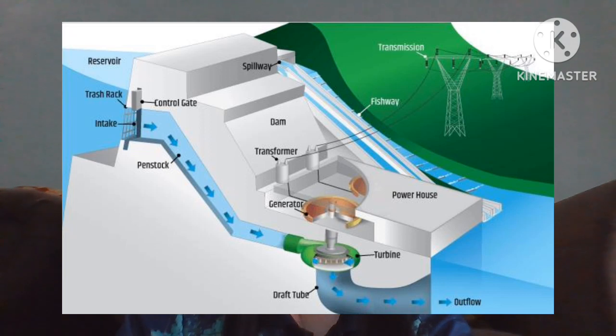The energy available from the moving water depends on both the volume of the water flow and the change in elevation, also known as the head, from one point to another. The greater the flow of the water and the higher the head, the more electricity can be generated. At the plant level, water flows through a pipe, also known as a penstock, and then spins the blades in a turbine, which in turn spins a generator that ultimately produces electricity. Most conventional hydroelectric facilities operate this way, including run-of-the-river systems and pumped storage systems.